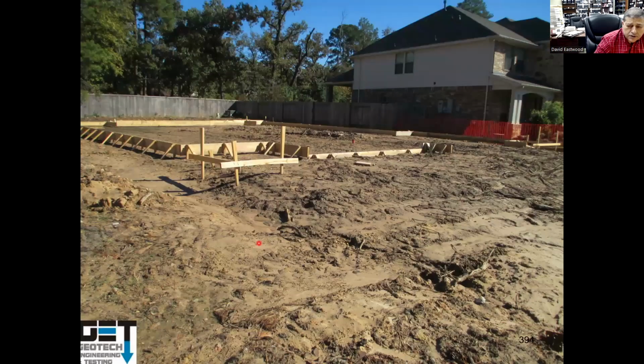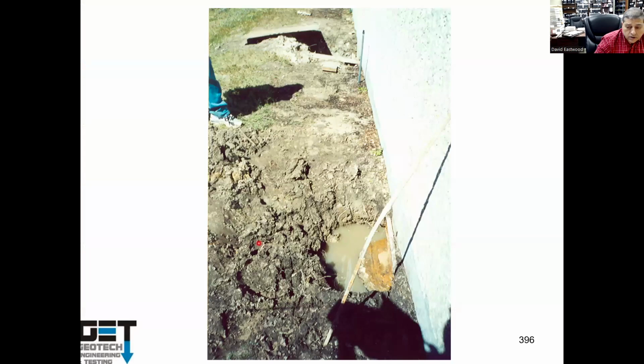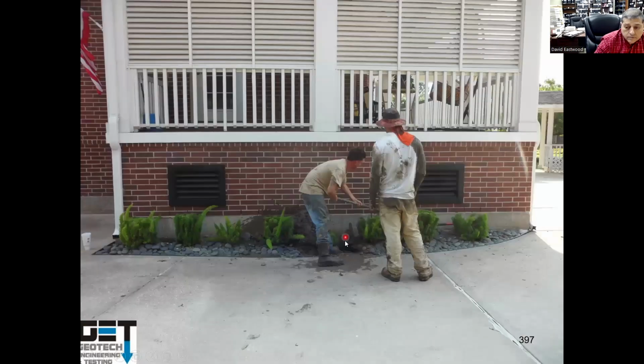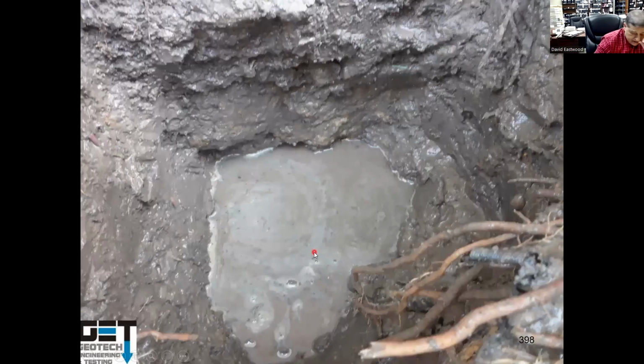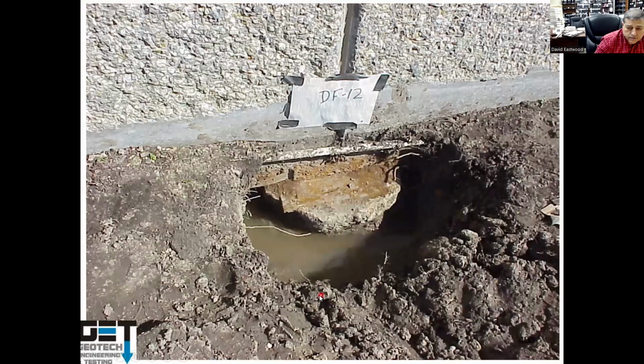So if you go out there and start digging your beams for your residential or commercial building, the beam gets filled up with water. This is called perched water table, and you develop that by having sand over clay. So you will have perched water table around piers, on the tilt wall building, in your planted areas, especially when you dig out next to some of these houses and you see water coming up under the slab. It's because of the presence of perched water table. Water is trapped underneath the slab and causes the expansive soils to move.